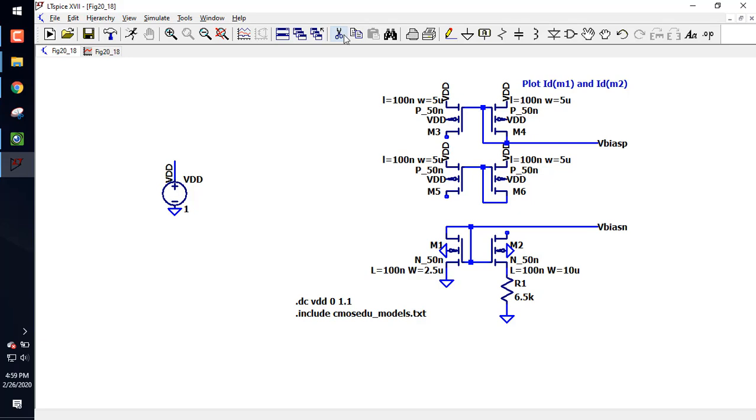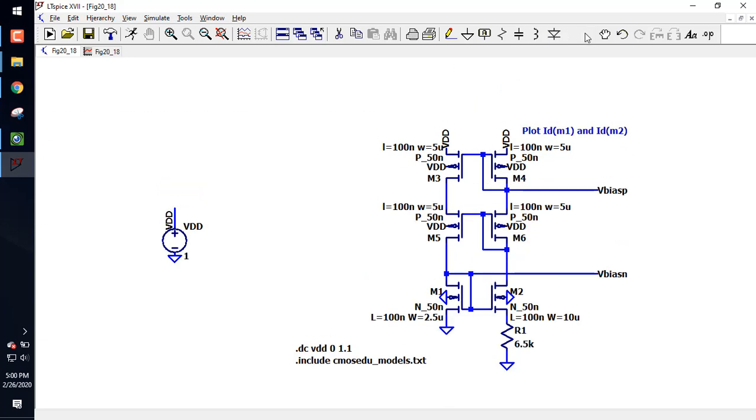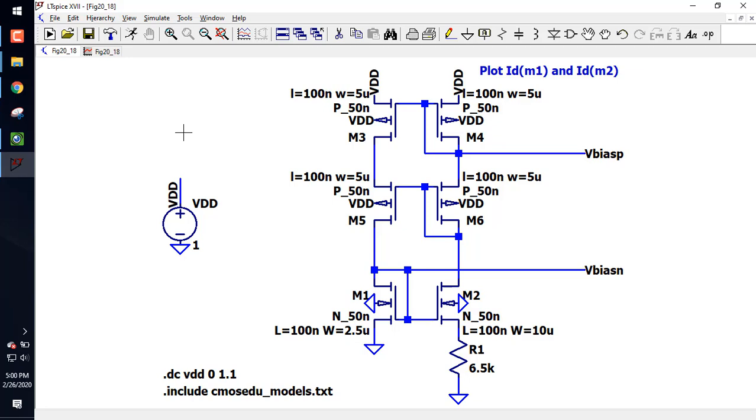All right, so let's go here. Let's get the scissors out. And I want you to tell me, first off, what do you expect is going to happen here if I cascode this side? So I have to try to keep these two currents the same, right? But when I change the VDD, don't I still change this voltage? And doesn't this voltage remain essentially constant? So it's going to be better, but it's not going to be perfect, right?